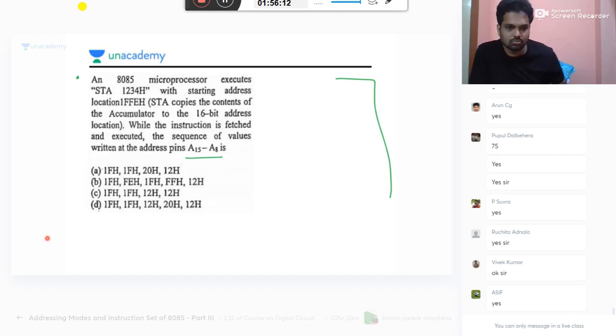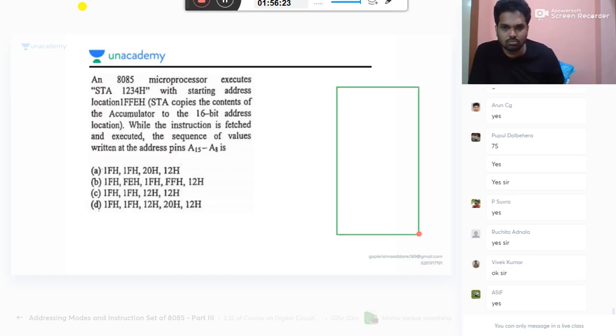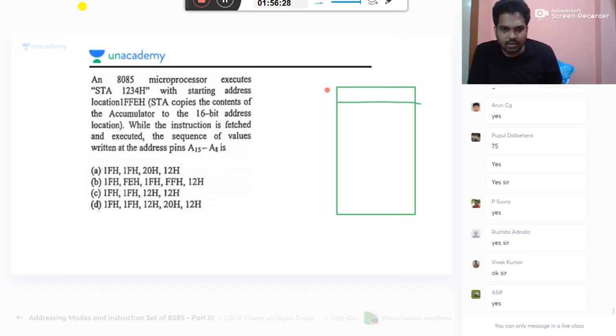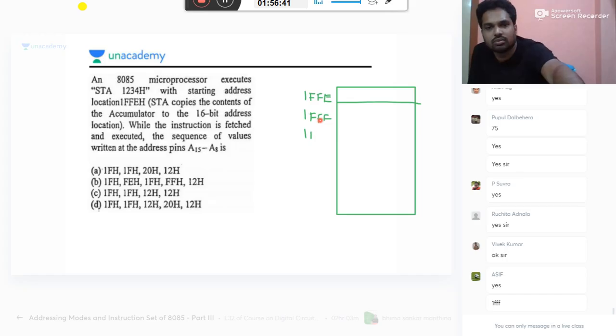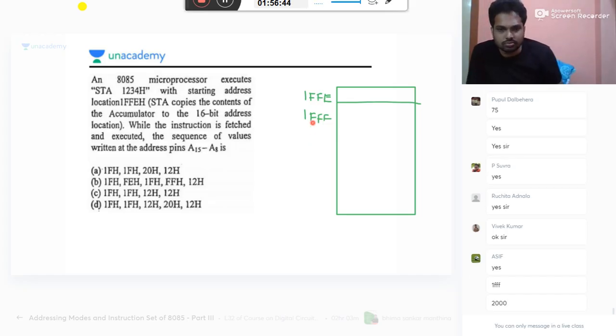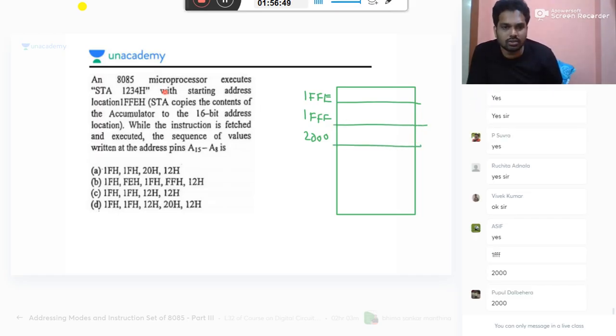This is where your data will be stored with opcode fetch of STA, like 32 hexadecimal, then what is that? 1, 2, 3, 4. Now first 3, 4, then 1, 2. Okay. Then what happens? It will go to the location 1234, and there some data is there, it will copy it. Okay, it is doing memory read, memory write now, store accumulator. Opcode fetch. This is what we discussed earlier.